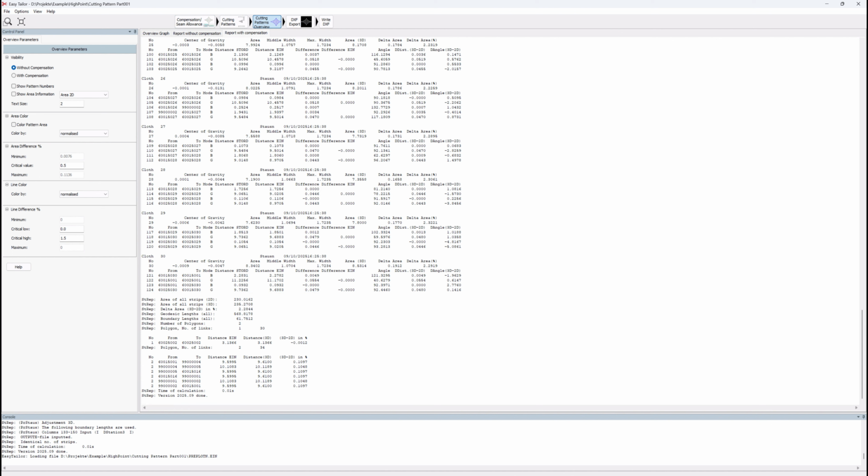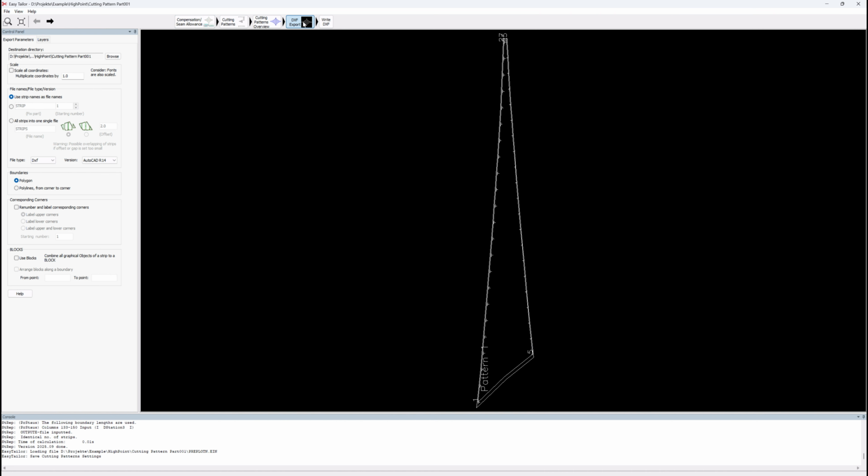After verifying all parameters, the final steps of the cutting process follow: the configuration and ultimately the export into a CAD system in DXF format. By clicking on the DXF Export button, the corresponding interface opens, where the settings can be edited and adjusted for the export. The first cutting part is displayed in CAD format. It includes the system line with compensation, the edge allowances, the welding marks, and the pattern labeling.